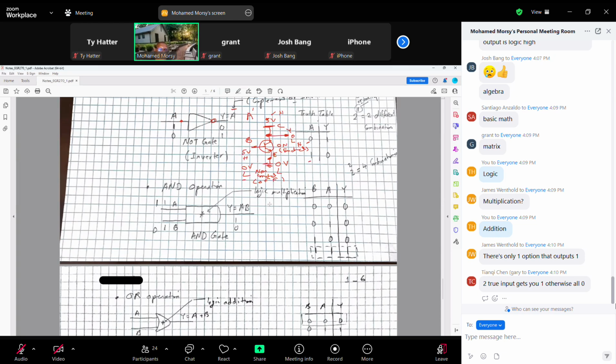This is not reliable at all, especially if we have a long bit stream. So what do we do? We look at the two input bit streams, and to draw the output, we look at where both inputs are simultaneously ones.